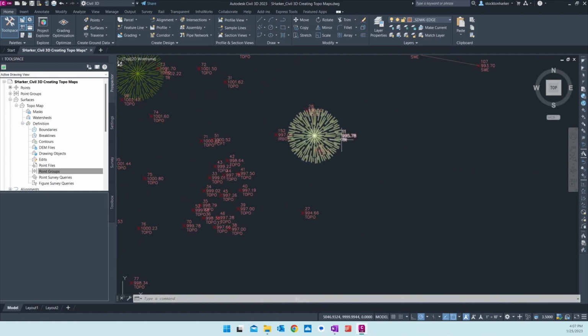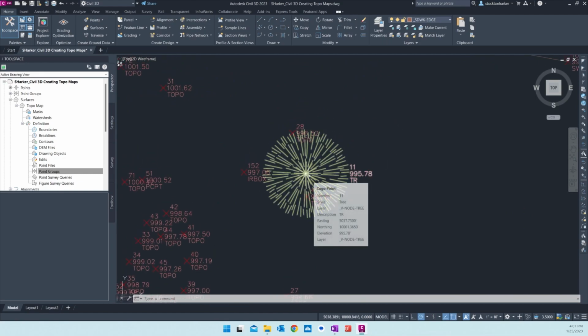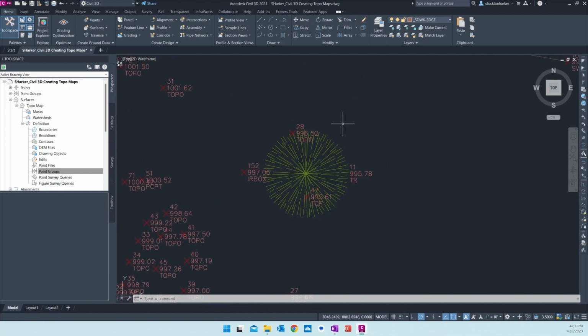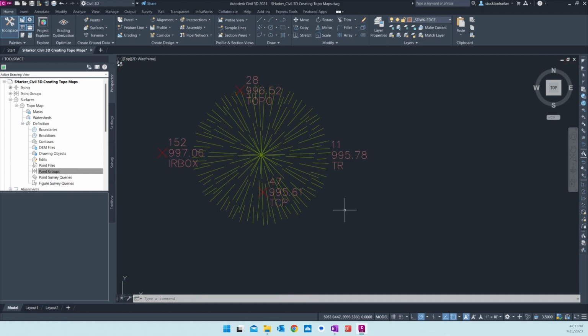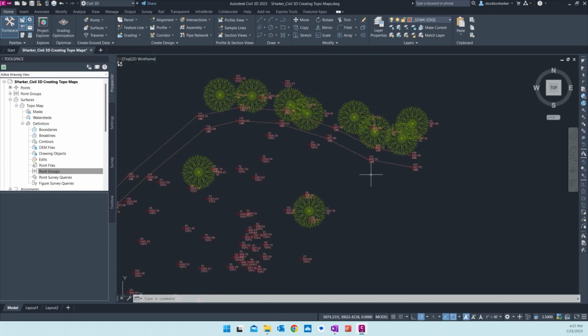We have trees. Now, since I did the survey, I know that when I took the tree data, the trees aren't in any type of special planter. They're directly on the surface. So I can include the trees and it will be part of the data. Same with the irrigation box. I know that that is part of the surface where I took it.